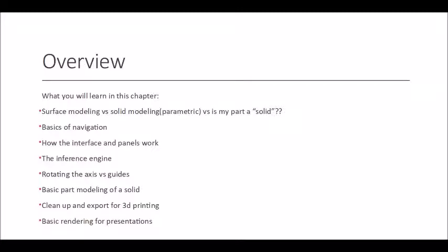So parametric modeling is if you were to update one single dimension in a part, everything else is constrained to that one dimension. It knows all the other information. So you update one dimension, everything is going to adjust according to that. But it doesn't always have to. You can actually make a dimension independent.